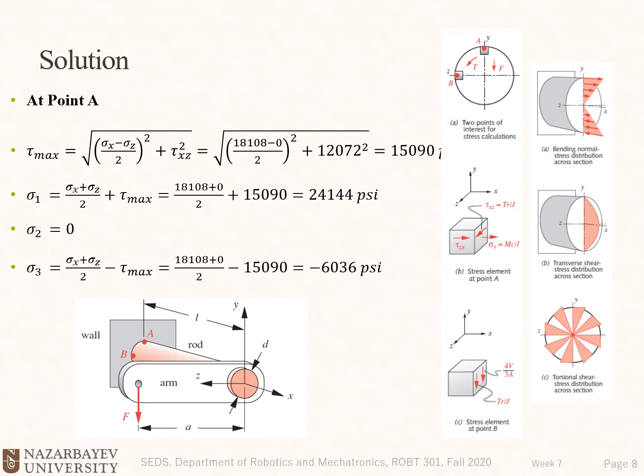Okay, so we'll do so. I wish you and recommend you to use Mohr's circle also. Not only look at these formulas, also use Mohr's circle to fully understand it first, plus you will see that you don't need to memorize these formulas. So if you use a Mohr's circle, we could find the tau max, which is the principal shear stress.